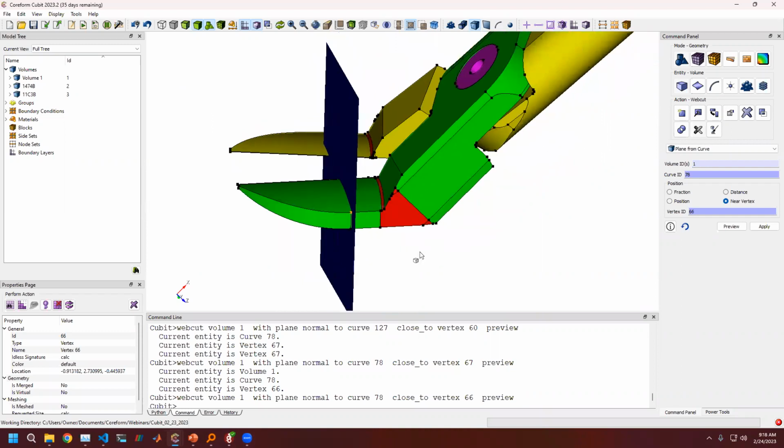And so we'll make that little Python script that finds these spline surfaces available after this webinar. But that's something I like to do: find spline surfaces, heal them if I can, but for the ones that you just can't get rid of, try to avoid doing further operations on them.